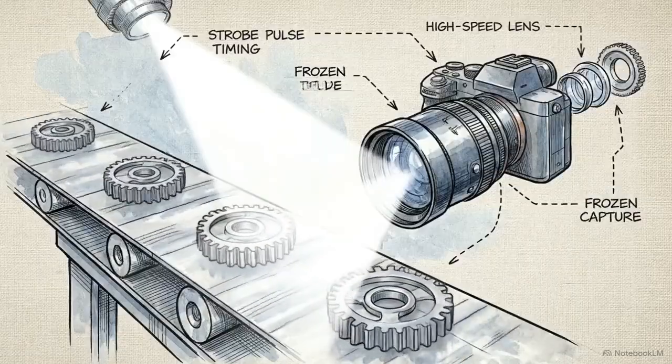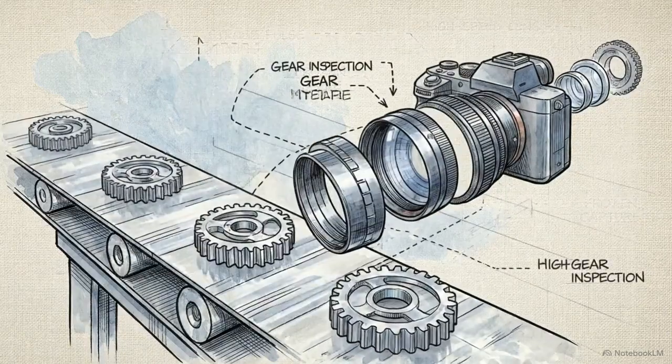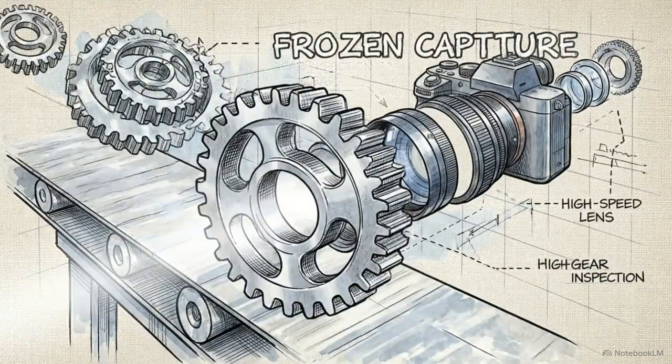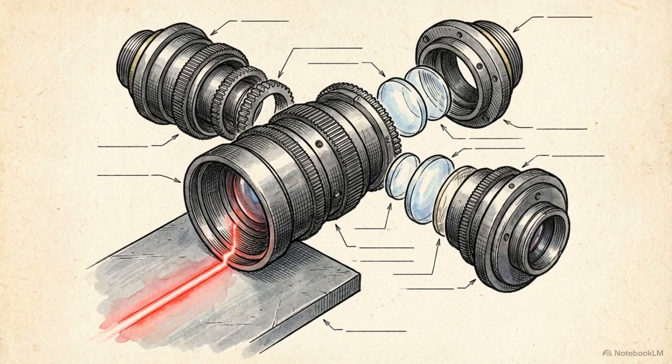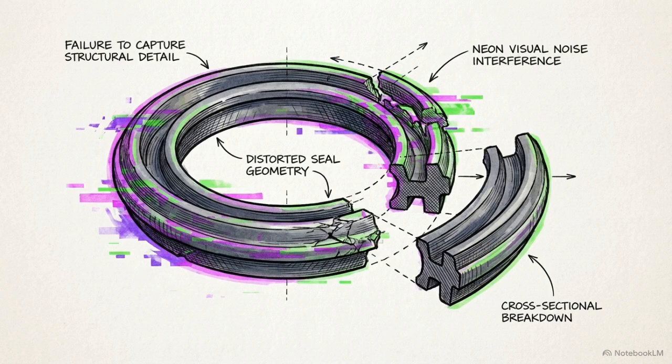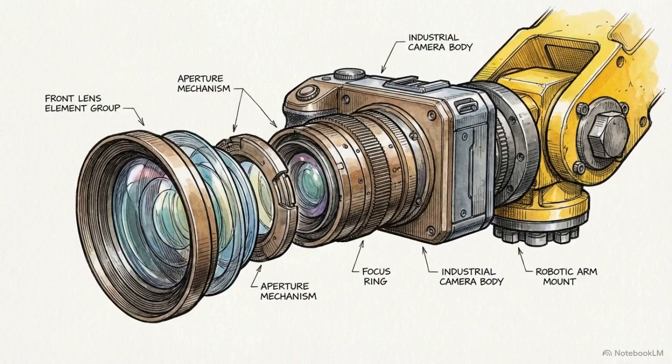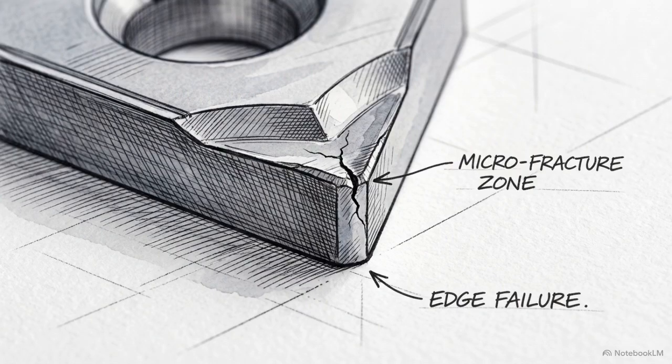The factory floor is defined by high speeds and variable ambient conditions. To process visual data, cameras must first eliminate motion blur entirely. Algorithmic success is entirely downstream of the physical capture. If the illumination design or the sensor's dynamic range fails to record a defect, no amount of software enhancement can compute a solution from missing data. The chosen hardware dictates the maximum achievable throughput. Inspecting CBN inserts, for example, demands high-definition visible optics simply to resolve the sub-millimeter surface defects that define a failure.